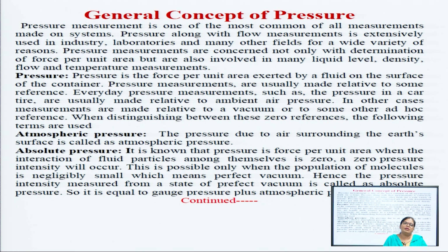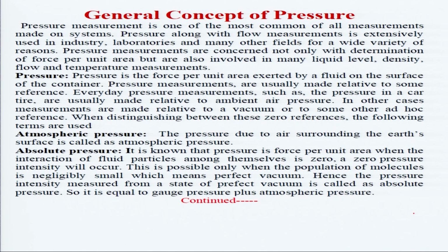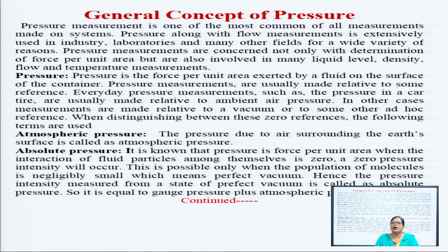So, before moving to the transducer part, we can discuss the basic concept of pressure. Why am I discussing pressure? Because we use many different types of pressure: vacuum pressure, atmospheric pressure, gauge pressure, total pressure, and absolute pressure. First we discuss what types of pressure we use, but in general purpose we use gauge pressure. From an industry point of view, we always measure in gauge pressure.